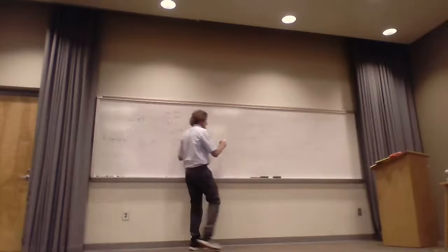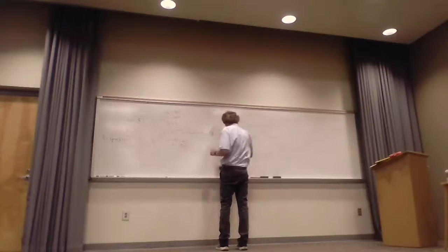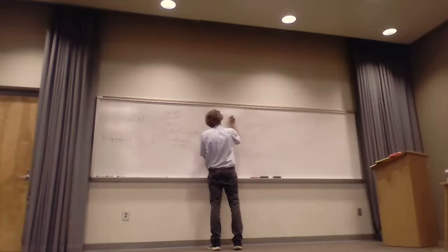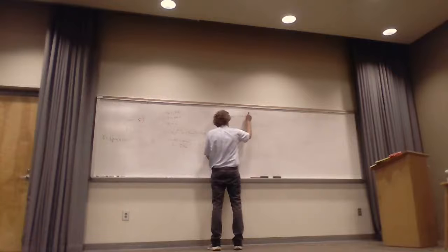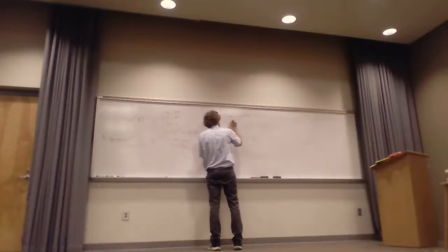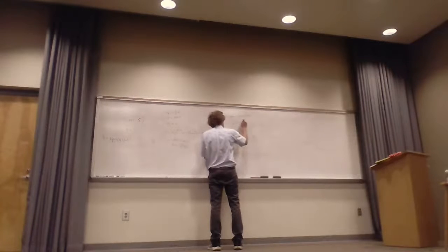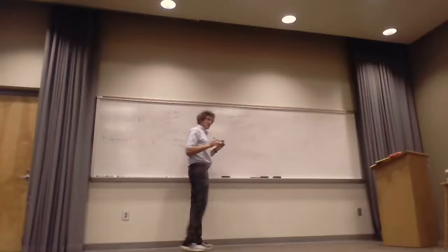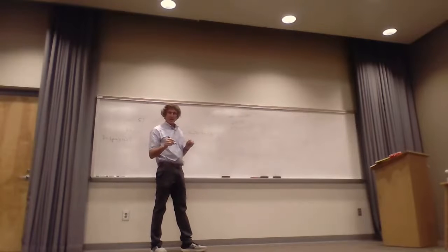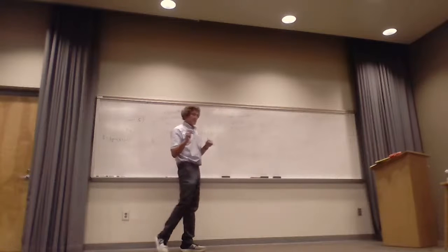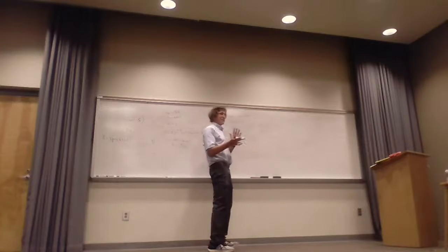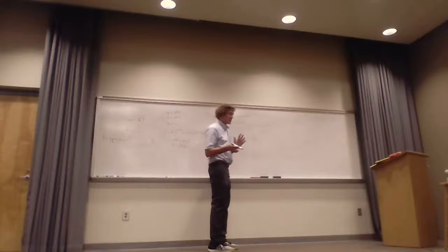A good conductor has conduction current much greater than displacement current, or really sigma much greater than omega epsilon. Does everybody follow me on this? That's a good conductor when the conductivity is much greater than omega epsilon. Let's just see if it is. If it's of the same order of magnitude, you can't make this assumption.